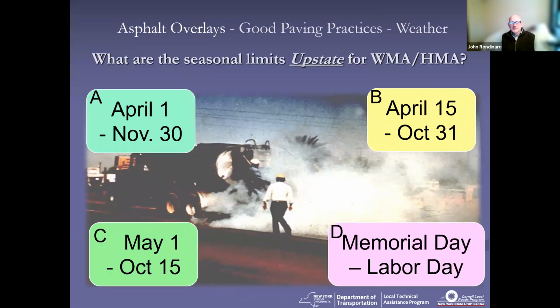For the compaction, somebody asked, is that thickness for the compacted thickness or the paver thickness? You're going to be laying it, you want that finished mat. So for your 9.5, you want that finished mat at 1.5 inches. And so the rule of thumb is 25% more on that 1.5 inches, essentially getting it up around 2 inches so that you get an appropriately compacted mat. So it's always compacted when we're talking thicknesses, because that's what we can measure later on anyway. So it's compacted thickness. Yep.